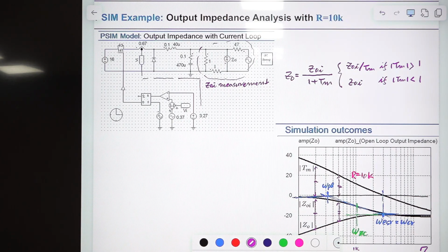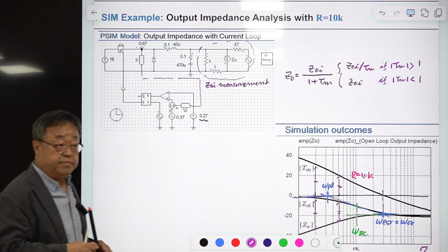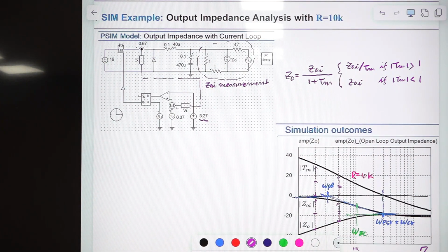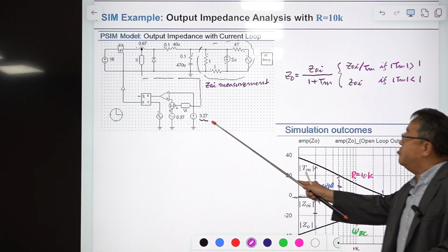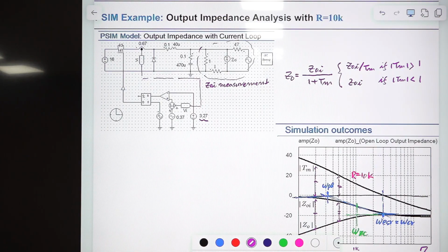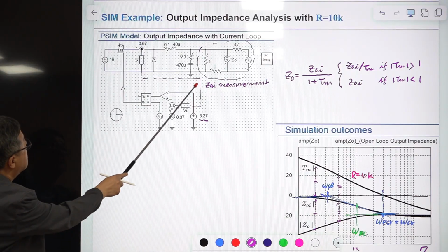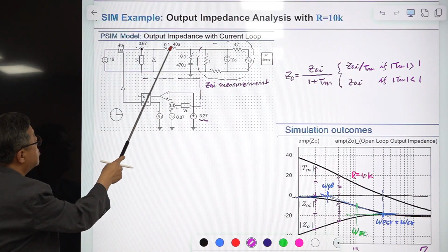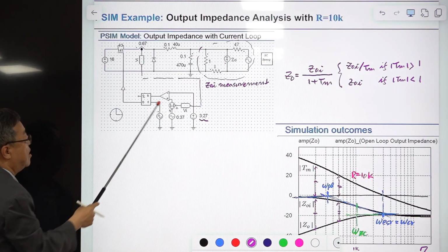And this is calculated from the maximum value of switch current, the current sensing network gain, the slope of the external ramp, and the on-time period of the converter. Combining these, you estimate and calculate this, and this becomes the DC component here, and the AC component is coming through this. This is to measure the output impedance. Somehow the AC component is coming through this and passing through this, and it generates the plot.